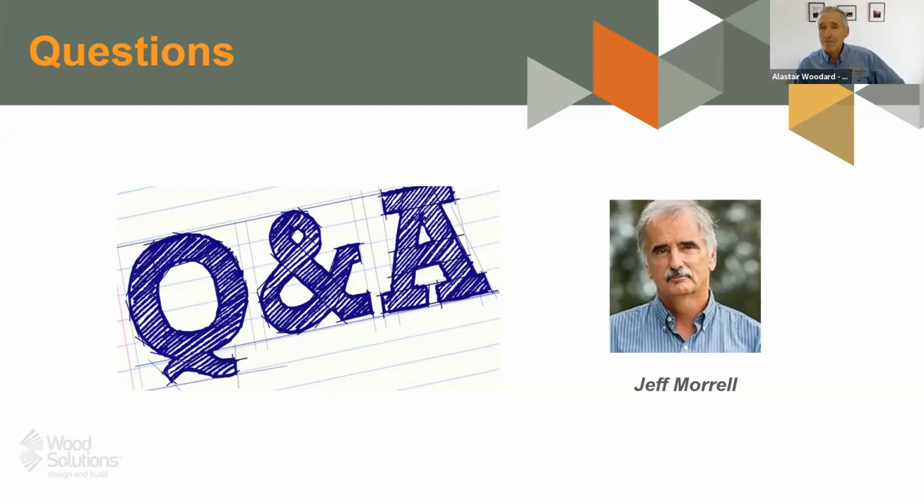Question here from Juliana: is it possible to completely remove mold from timber, preventing health problems in a building? Yes. So mold is a water issue, really. If it's a small amount of mold, I would just take a little bit of soapy water and wipe it off and it would go away. If the wood stays dry, the fungus isn't going to grow back and it's probably dead by then.